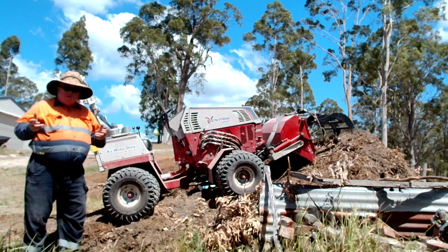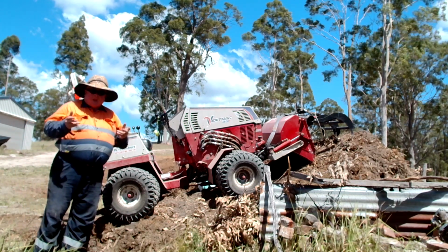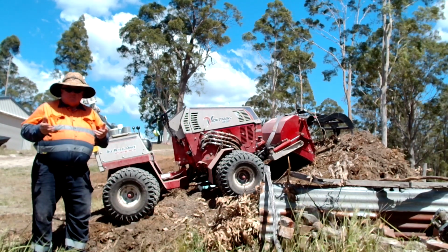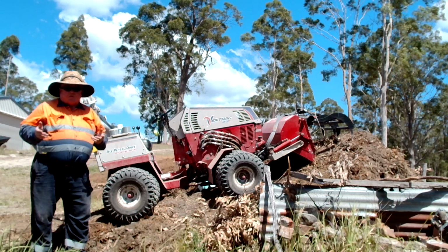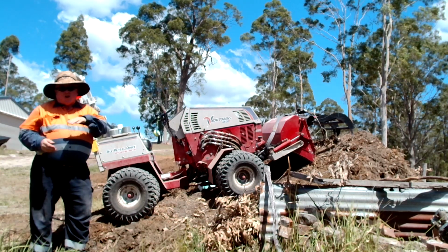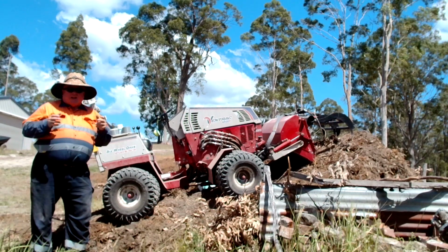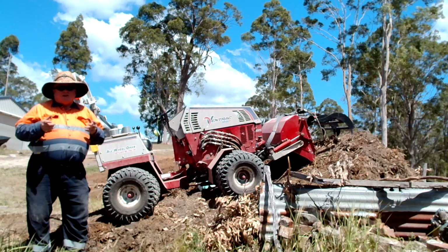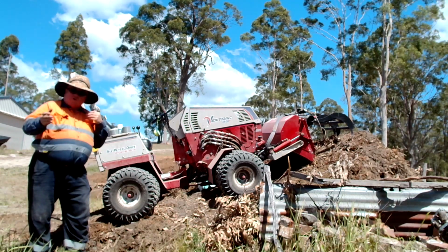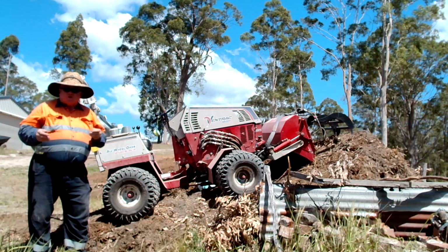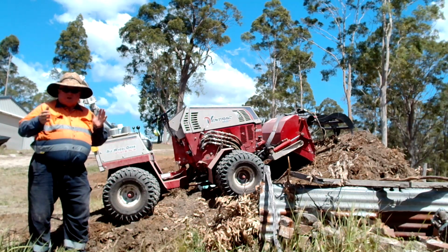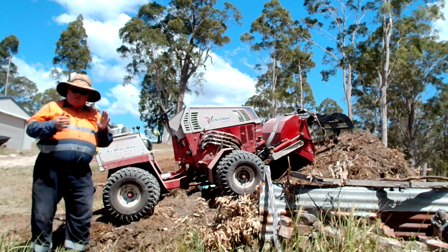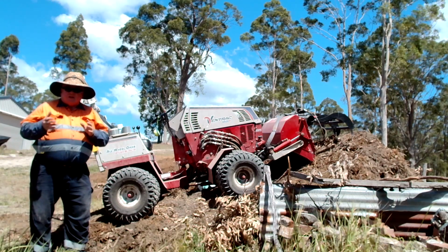Now why 1 in 4? Because it happens to be the sort of grade that's used for the production of drifts in underground mines. A drift is an inclined tunnel leading into the mine, and it's inclined so that vehicles can drive up and down. The complication is the shallower the grade, the longer the drift, and the higher cost to produce it. So mines try to optimize that length but still be able to use vehicles. And 1 in 4 is the general accepted grade.